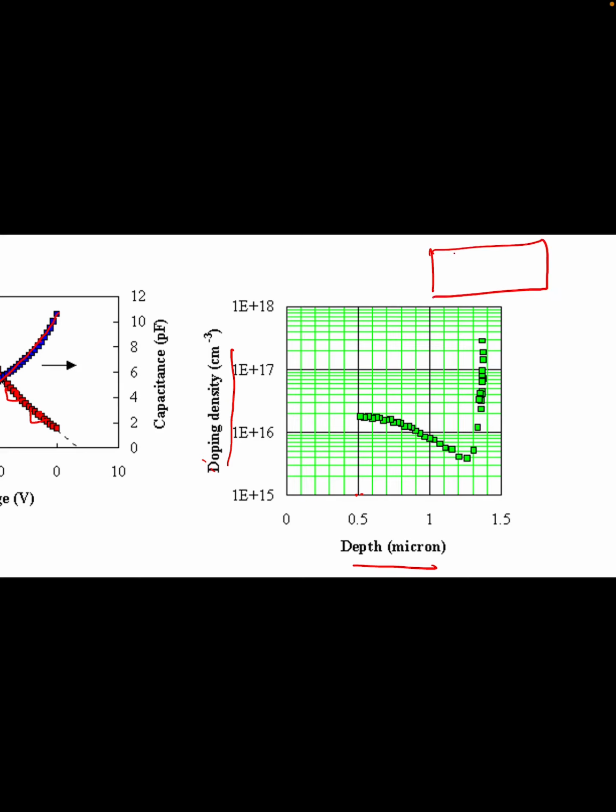and see that if I have a PN junction like this, and I have an N side which is super heavily doped, I am now looking at the doping density from x equal to 0, because N is considered to be super heavily doped, so you do not have any depletion on the N side. I am looking at the doping density on this side. So you can see that there is some missing information here.